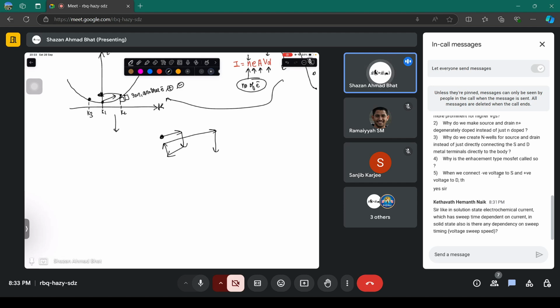And that is why I brought the concept of something called ballistic. Ballistic means if you make the channel so small that just one of these scattering events happens, whenever an electron encounters another electron it gets scattered, but the channel length is so small, of the order of the scattering length, that the electron directly goes into the drain. After scattering, it does not even hit any other scatterer. That is something called ballistic, where the resistance drops almost to zero. There is no resistance there.